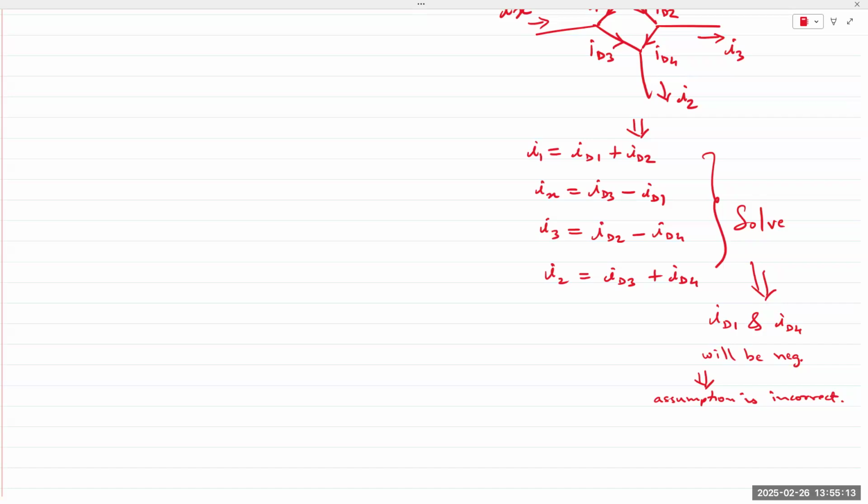Okay. What seems like the most logical assumption to make out of those 15? There are 4 diodes, D1, D2, D3, D4. We obtained 2 currents positive, 2 currents negative. What makes the most sense as the next assumption? That's possible, yes. So all diodes off is a possible choice.